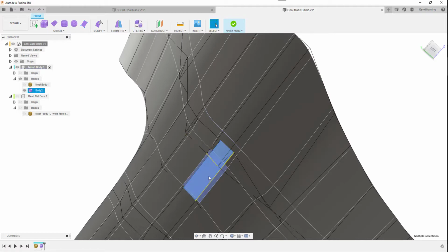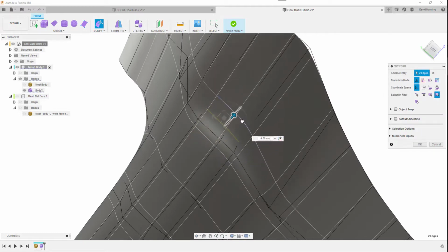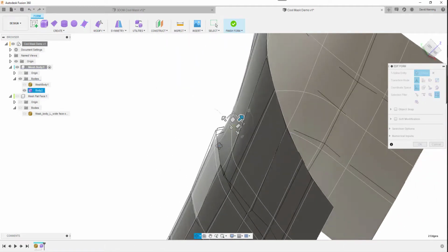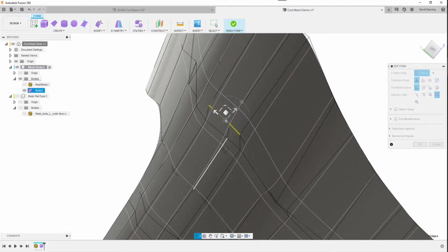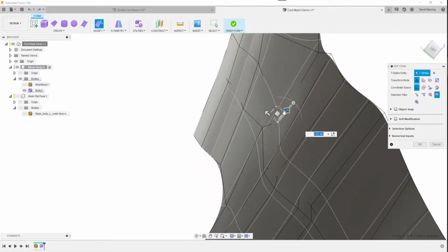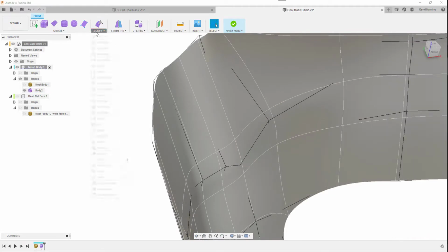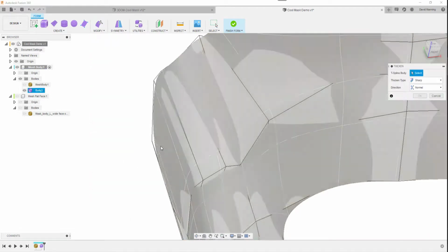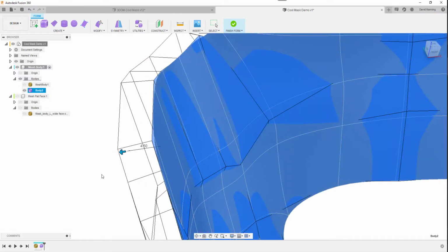Now there's other ways to do it, but the easiest manual way is to select those, go back to your model. You can use the control lines to modify your mesh, and I can adjust that, and I can maybe move it out, or I can move it in, or wherever it needs to be to make it look like it should. Similarly here you can see that intersection point is overlapping, and if I clean them up, hopefully, if I do a thicken again, thicken that way, go OK.